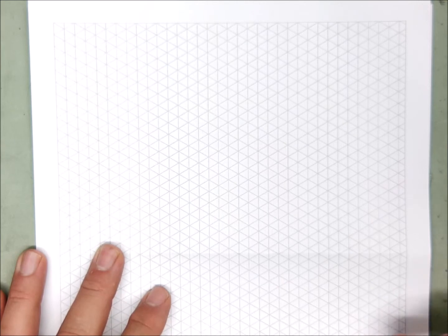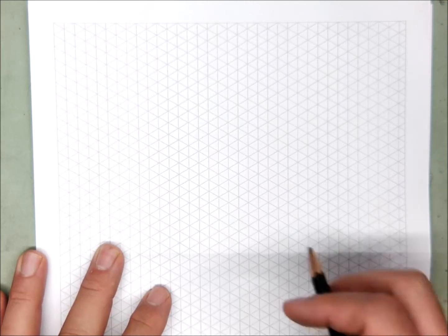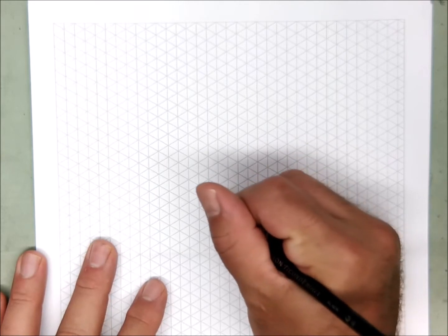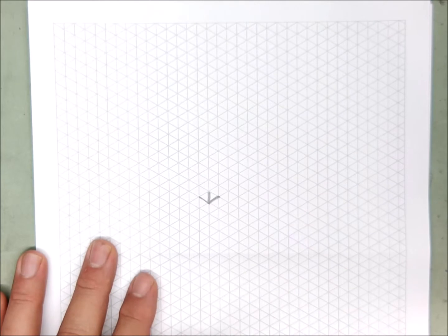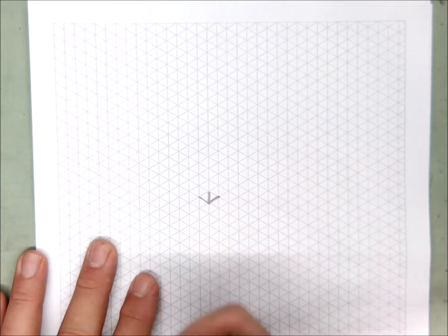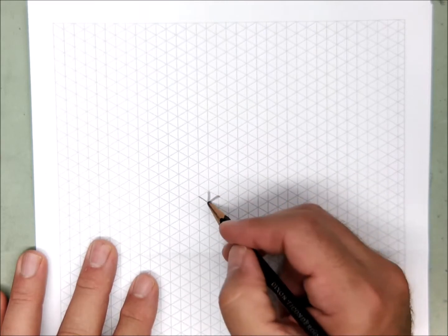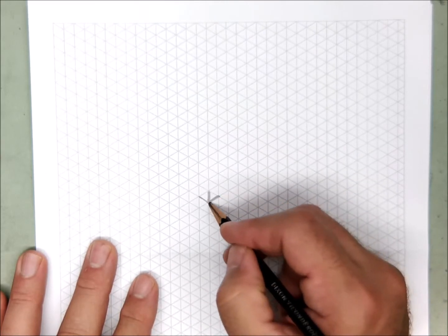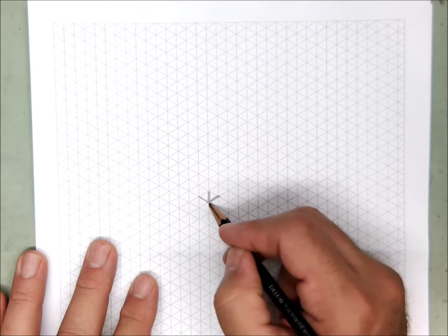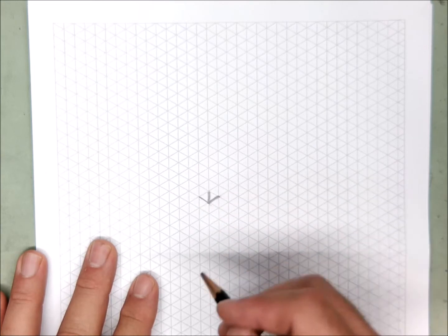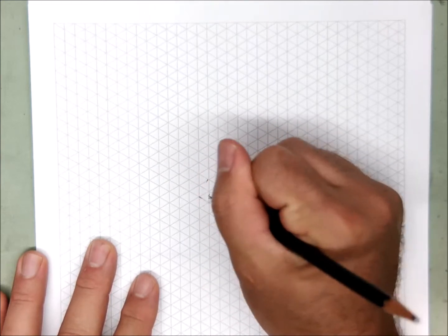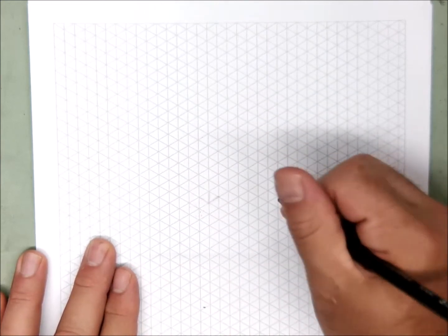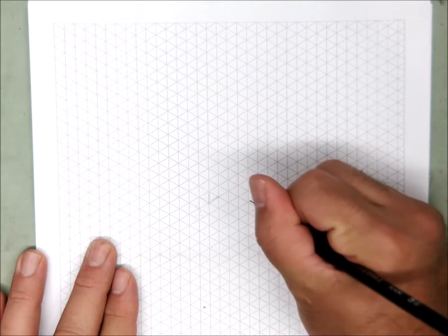So, the deal with isometric is everything starts out with that shape right there. I call that shape the chicken foot because it looks like a little bird's foot or something. Three lines. Pick a point and go up, vertical, up to the right, up to the left. Both of the inclined lines are at 30 degrees. You're going to follow the graph paper. And the location where you pick, I'm going to pick a little bit off center, down to the right of center.